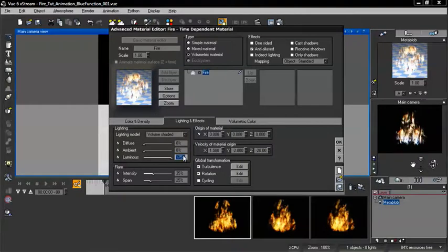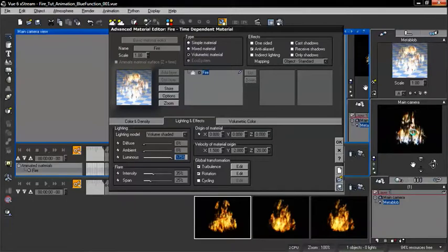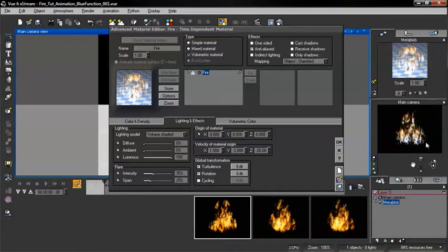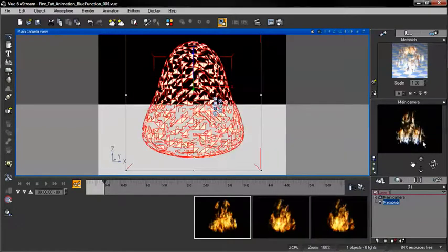So if we need to, we can bring down our luminous setting to 150 and start to see more of our color again. And we can see that overall that hasn't changed too much, so we could either bring that value down a little bit more, or we could edit the actual color node in our HLS shift and bring down the luminosity, and that will also balance everything out. So you can see it's actually fairly easy to make our overall color change, and it looks pretty good.